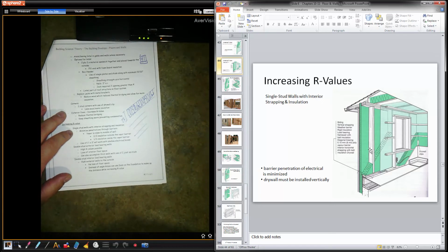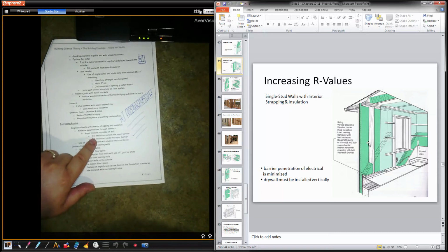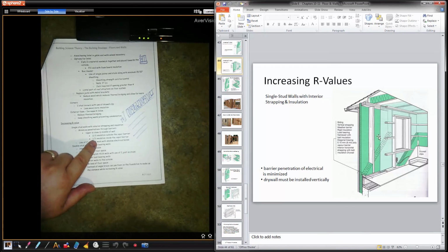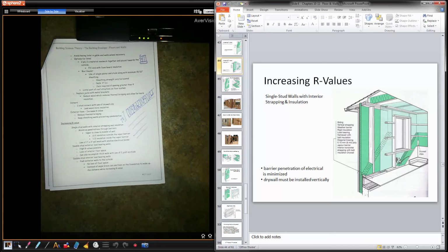So the outside wall is always going to be bigger because we need more insulation on the outside. You can see here 2/3 insulation on the outside of the vapor. That's the vapor. And we have 1/3 of the insulation on this side of the vapor, which is okay. And all the wiring is on the warm side of the vapor, which is ideally what you'd want. That way there's no conduction through metal wiring. So I've done a lot of houses this way.